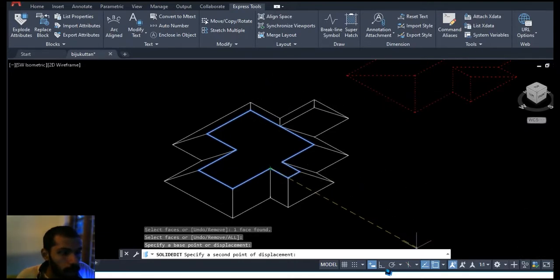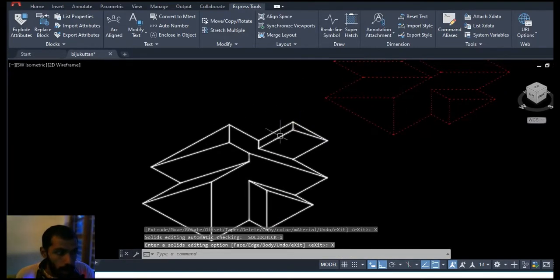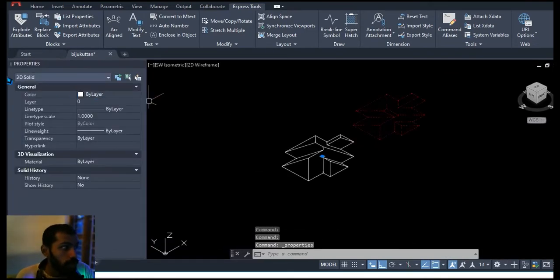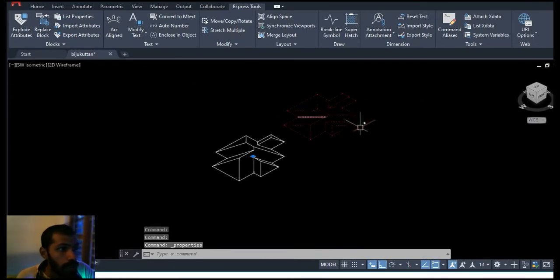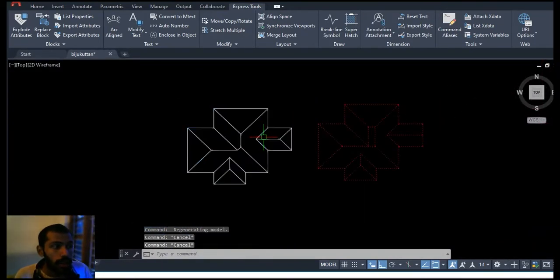And you want to turn on the ortho. That's right here, and probably you can click anywhere right in here. Alright, the thing is 3D right now. If you get into the properties of this object, you can see that it is a 3D solid right there. If you again get into the top view, that is a 3D solid. And first let's check.